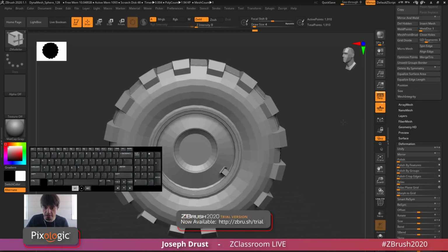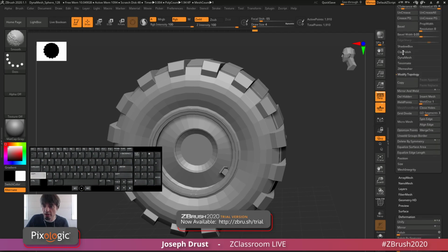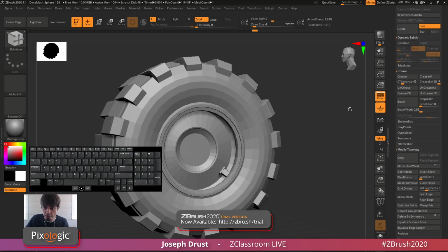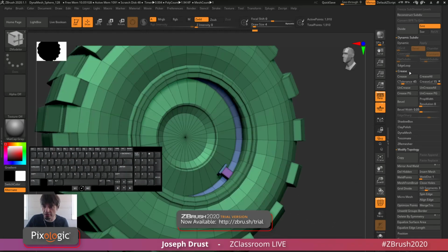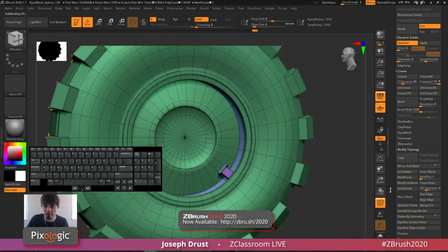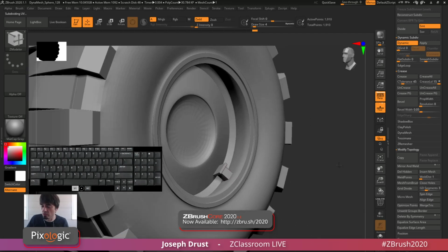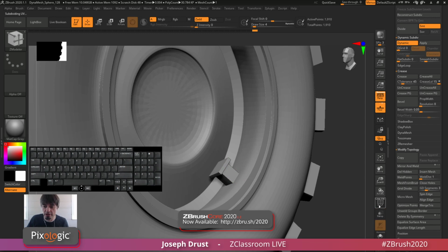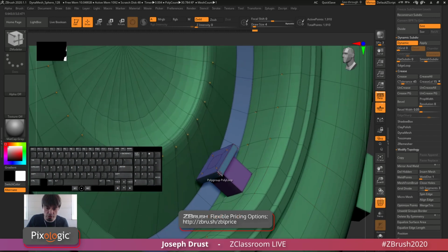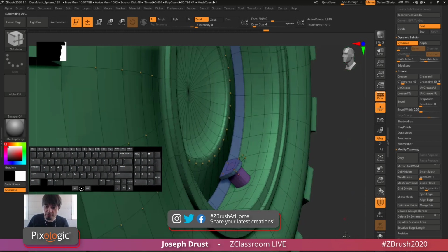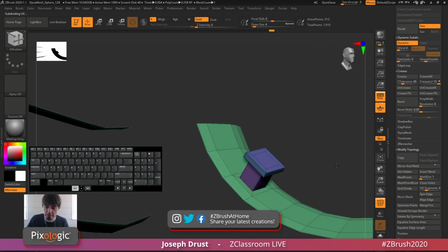Now at this stage, I'd probably go through and start doing all my creasing on the model here. So applying a bunch of creasing. You can do it first by edge angle, which is going to look pretty decent right out the gate. You can see that since that square area was all the way square through there, you probably don't want creasing on that. So I would have to come back in and uncrease these. Let me get my crease option here. And then this will now go back to that roundness. And you can always use visibility to select these things a little easier too.